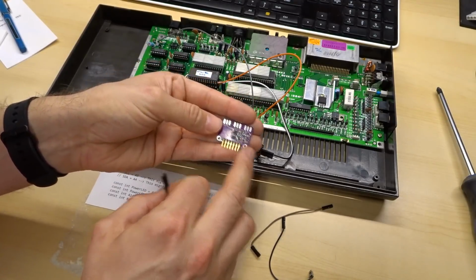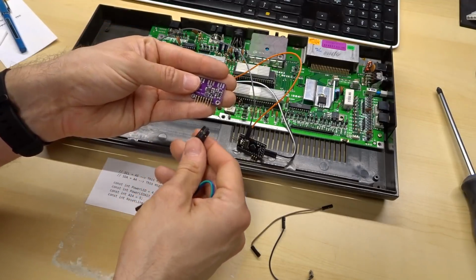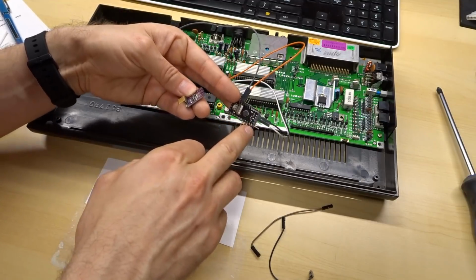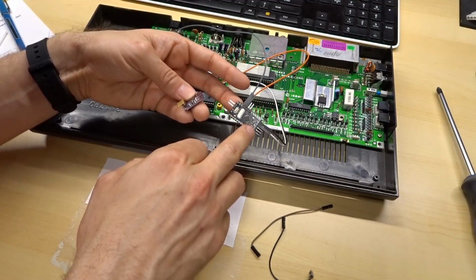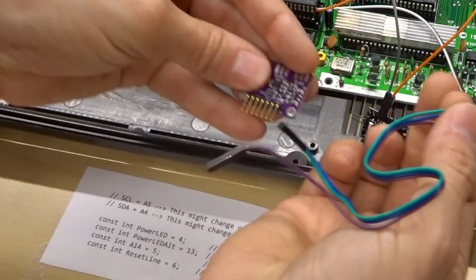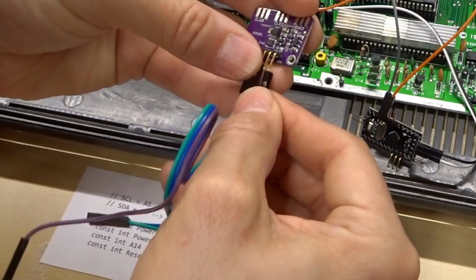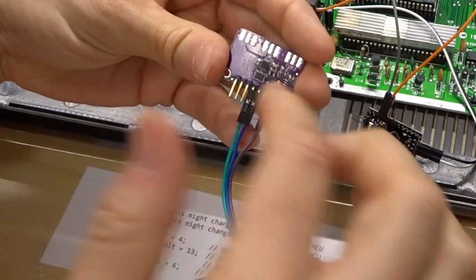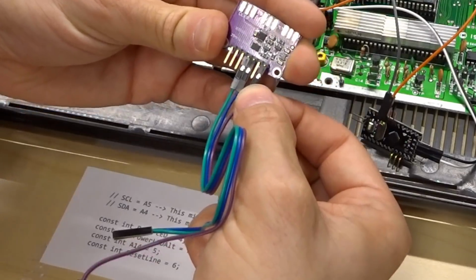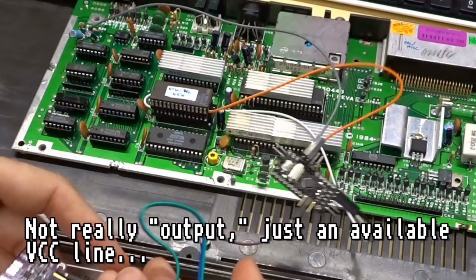Now remember I said I take the ground for this off of the motherboard right near the TED chip. That ensures a good clock signal. But the VIN, which is the voltage, I do take off the Arduino. So I have an extra pin soldered on the Arduino that allows me to feed the voltage, because there's a voltage pin here and there's another one over there. So I have these wires to go to the Arduino, and it's a little hard to see. So SCL, SDA, ground is the one I don't have connected, and then VIN is the purple wire. So the purple wire is going to connect right there, which is the VCC output of the Arduino.